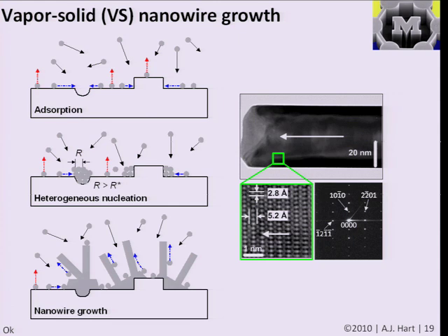And what happens is if you have a substrate sitting inside a vapor atmosphere, and this is a picture of a zinc oxide nanowire, which we'll see on the next slide can be made by this method, and you expose the substrate to a vapor of the desired precursor atoms. So in this case, it can be zinc in an atmosphere of oxygen. These basic processes of atoms adsorbing on the substrate, diffusing across the substrate, and desorbing from the substrate happen.